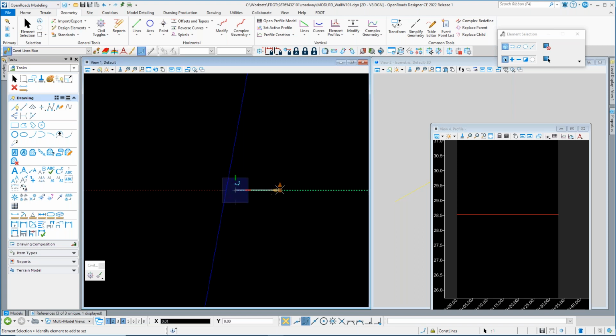Sometimes it works, sometimes it doesn't. You can trim it back a little and it might work better that time. There you go. See, it worked on the second try. I found out that if it's a little bit too close and you want to drag it with that slider, it doesn't always work. You got to come back just a little bit more because of the tolerance in there, and then it seems to work out pretty good. Or you could use the circle manipulator and grab it and do an intersect snap. It's always an option.